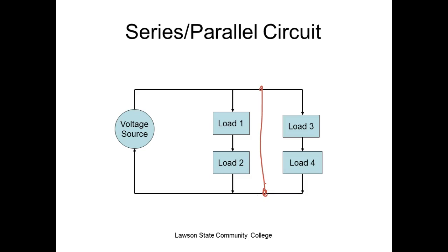So now the only thing that's limiting the flow of the current is the resistance of the wire. So we have something called Ohm's law, and this is where we can calculate the amount of current, and we take that, so I is equal to V over R.